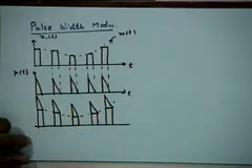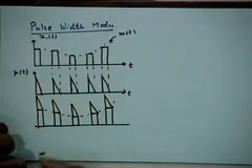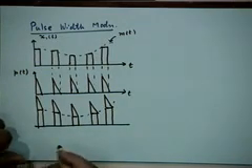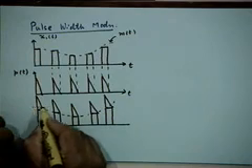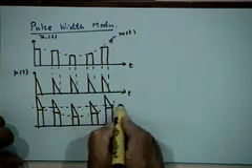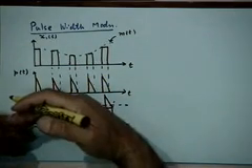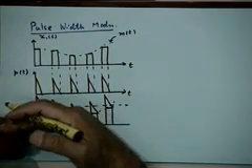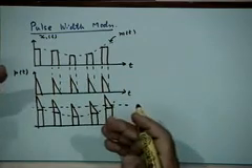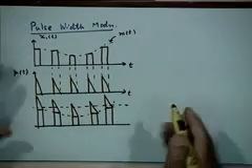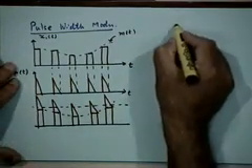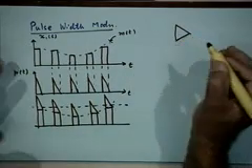Okay. So, you are likely to generate a waveform like that when you add up these two. Having done that, all you need to do is slice this waveform at some point, right? Have a threshold, and pass this signal through a comparator. Let's say you have heard of a comparator. A comparator is a device, basically an open loop operational amplifier that serves as an excellent comparator.